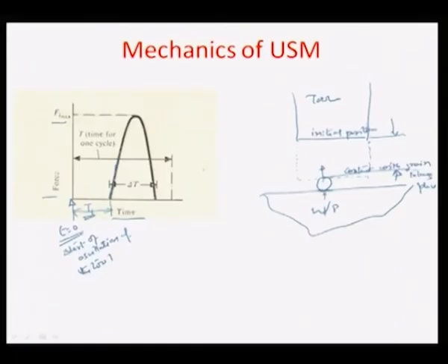Okay. So, the force is continuously increasing all the way to Fi max, okay, and the Fi max per unit area of indentation is really the ultimate flow stress of the material. So, Fi max per unit area of indentation can be equated safely to the ultimate flow stress of the work material.